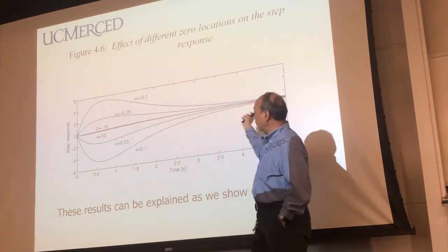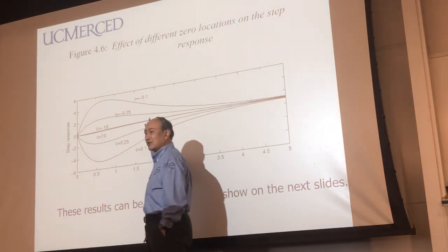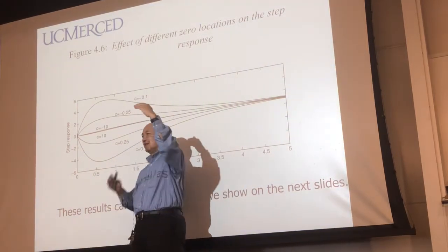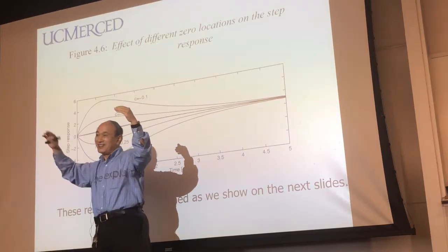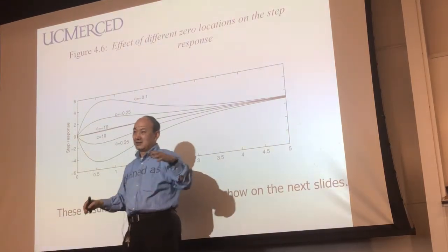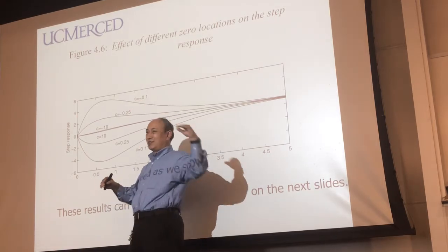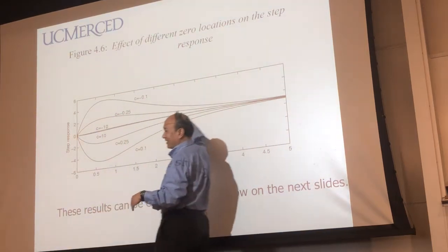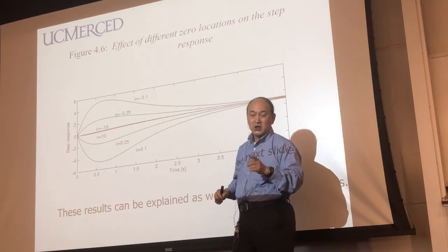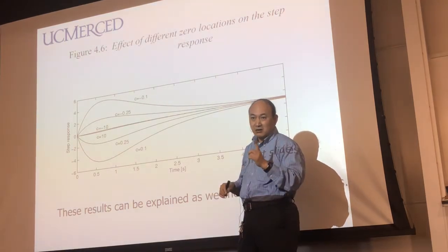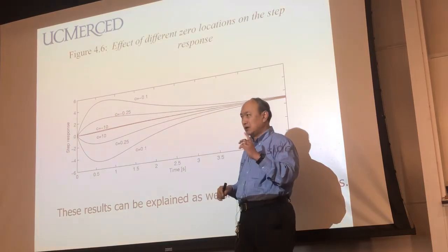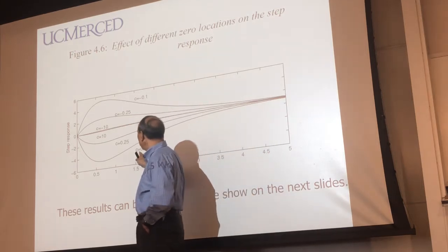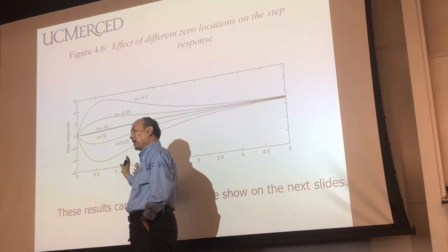But there are different ways to get there, and this is called the transient. Usually when you give a system a step, the system will respond; it's called the reaction curve. But I don't like it when I give you a step and you go the opposite way, then come back again. That's called undershoot. It has nothing to do with the pole. It only has to do with the zero, when the zero is on the right half plane.